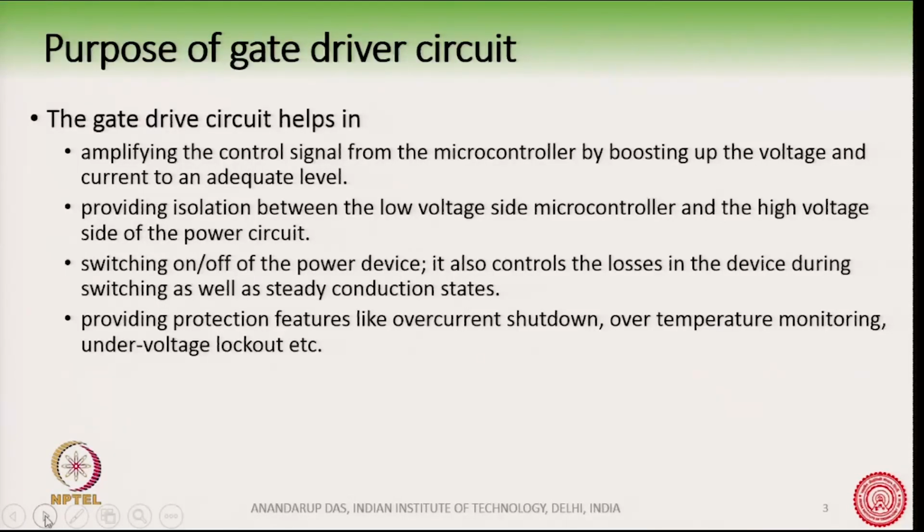This is also one more important function. Modern day gate drive circuits come with a gate driver IC, and they can provide a lot of additional features, and most importantly many protection features like overcurrent shutdown, over temperature, under voltage lockout, etc. These protective features provided by the gate driver ICs are often very useful while running the converter, and as a result the gate driver circuit is one of the most important and integral parts of any power circuit design.